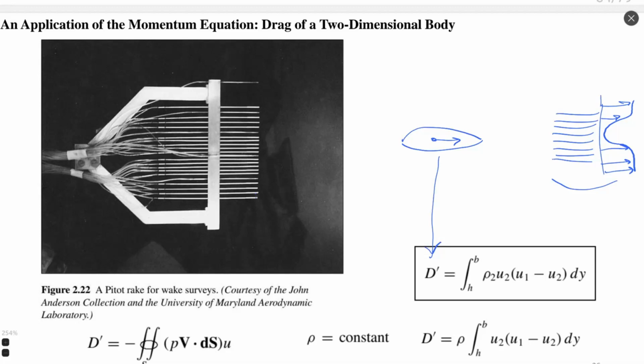We can use a small scale model of an airplane, introduce it inside the wind tunnel and see the distribution of velocities, and analyzing the distribution of velocities far behind this airplane, we can draw a conclusion about the values of drag force over this airplane. We are not limited by complexity of geometry, I think. We can measure something indirectly. It gives a lot of opportunities in experimental aerodynamics.